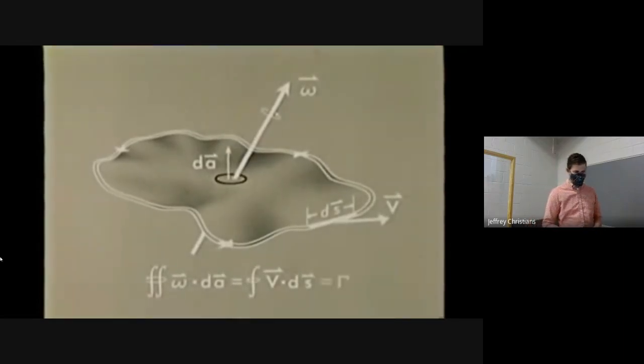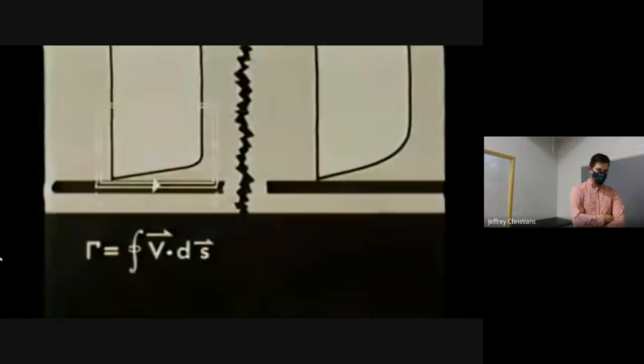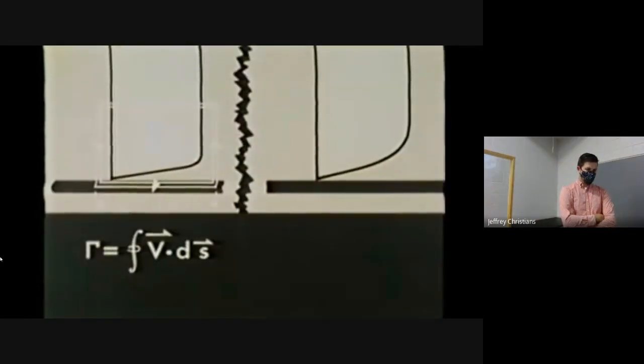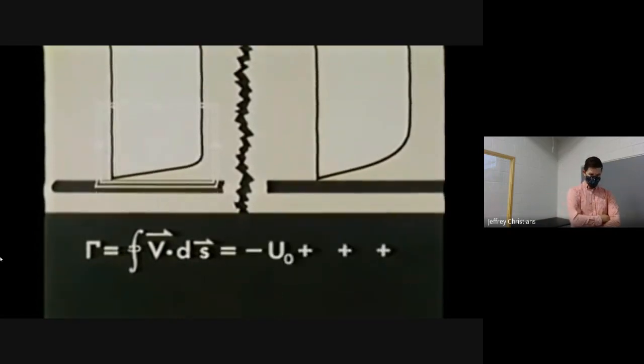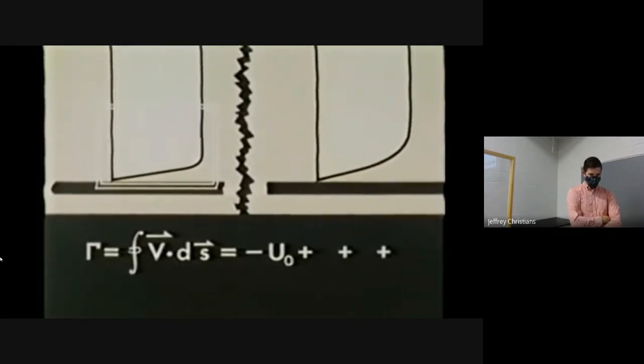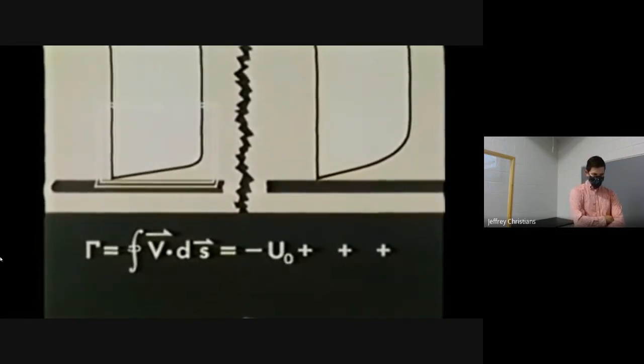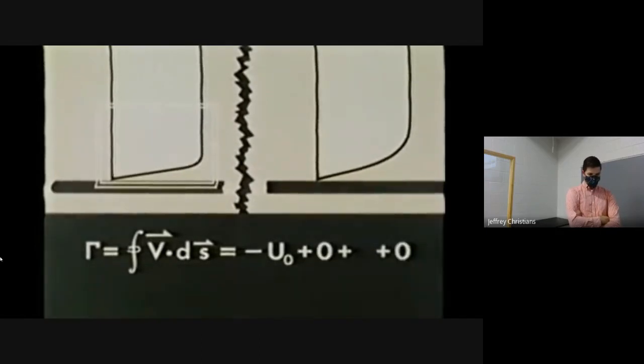The circulation gamma is the sum of the vorticity enclosed by the contour. The contour at the upstream station is a unit length along the plate and is more than a boundary layer thickness in height. At the top, the local velocity is parallel to the contour, but in the opposite sense. The components of velocity along the right and left parts of the contour are virtually zero.